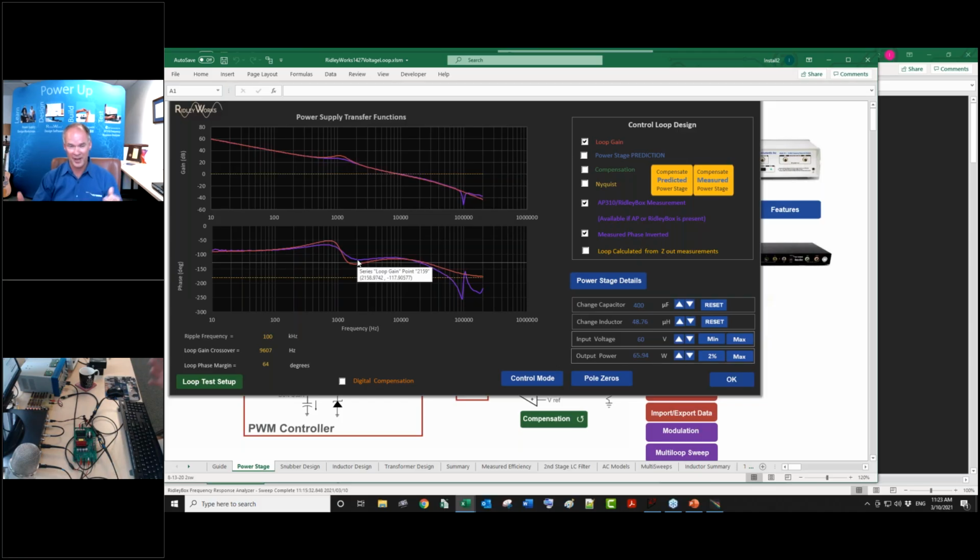And you can do a PhD dissertation if you like, trying to match this Q, but nobody cares, because there's the Q in the forward path, the Q in the return path. It cancels out. And you're not going to change anything about this industry by getting that Q better. The models here, as you start lifting up the loop gain, there's so much ripple comes through that the phase deteriorates when the model says it won't. So you push 20, 30 kilohertz, and it's like, well, what happened to my phase margin? It said I should have more, but it doesn't. So yeah, the modeling is just not that accurate.